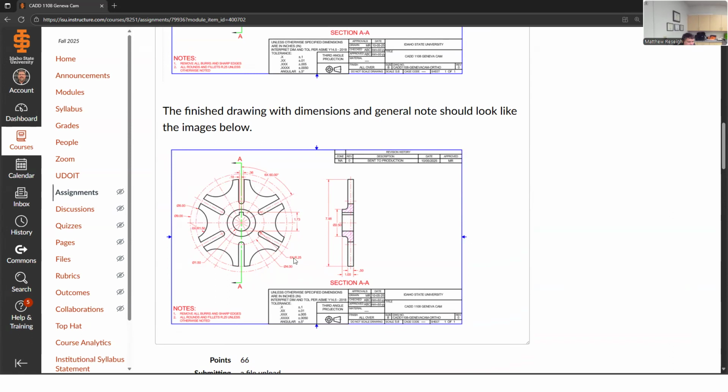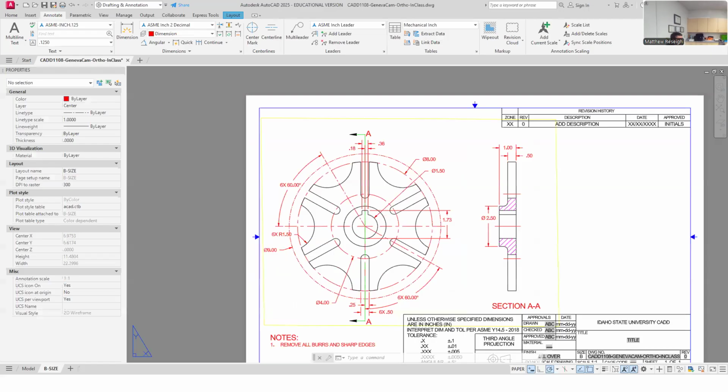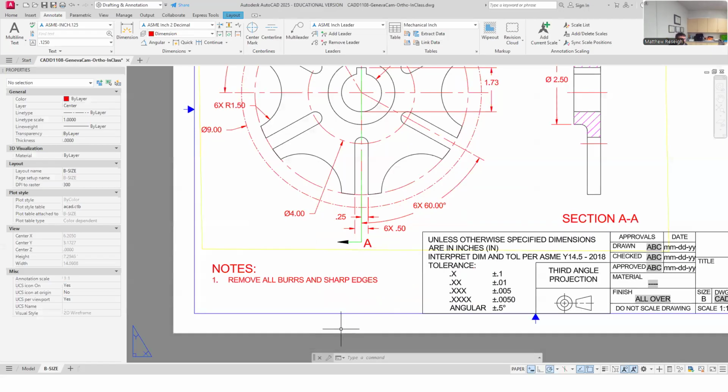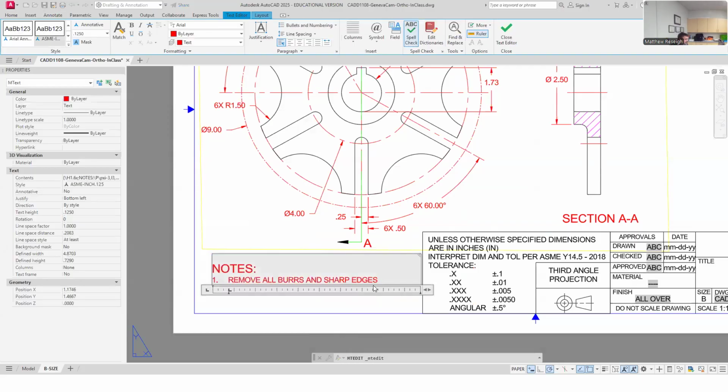I didn't add this, and I didn't really add this fillet, and I didn't size the fillet here. So I need to make sure I add that there's a 1/4 inch radius unless otherwise noted. Yeah, I don't have to really add the unless otherwise noted. That's generally understood. It's a nice little phrase to add, but it's kind of an understood statement. So I think I can omit the unless otherwise noted, but I do like to add that there is a radius if there's a radius.